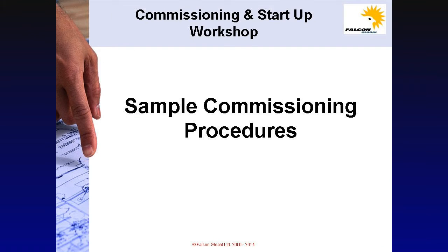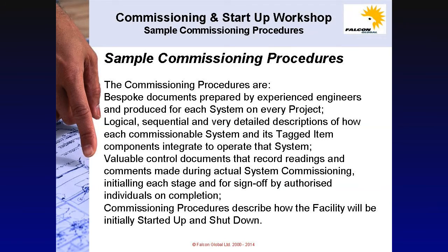Sample commissioning procedures. A commissioning procedure is a bespoke document prepared by experienced engineers and produced for each system on the project. It is a logical, sequential, very detailed description of how each commissionable system and its tagged item components integrate to operate that system.